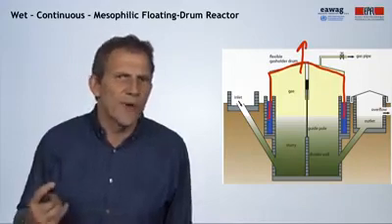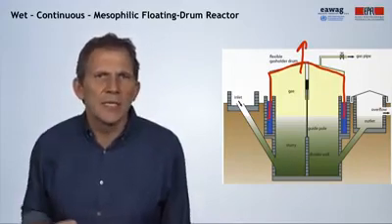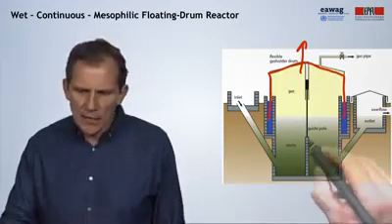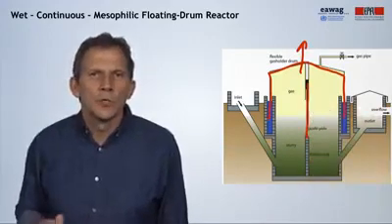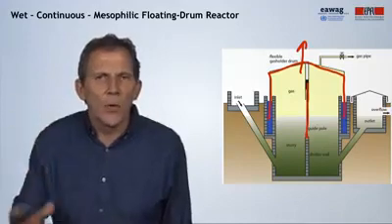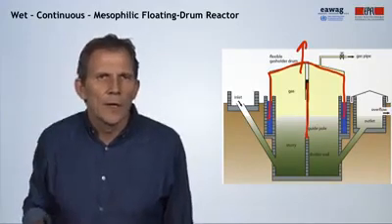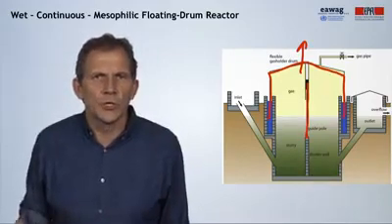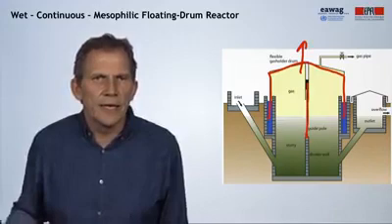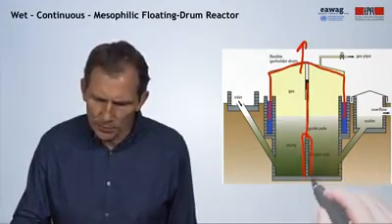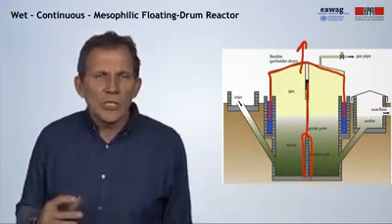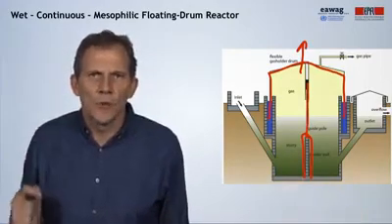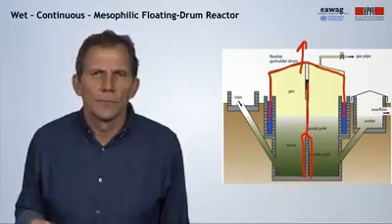It can also be made out of fiberglass-reinforced plastic or galvanized sheet metal. In this design, there's also a guiding pole to stabilize it while it's going up and down. There's also a divider wall, which helps to avoid short-circuiting of the slurry from the inlet to the outlet. You see it here. The digester is often placed below the ground, while the gas holder drum is above ground.